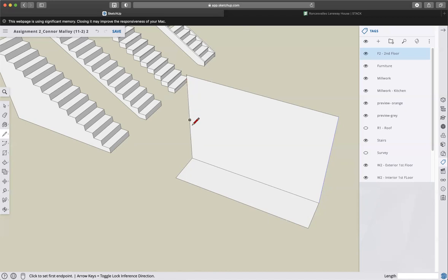The left-hand side is still one line segment. If I go to this side, every green is the endpoint. Those are now, that one side of that wall is now 15 separate segments. And that represents the height of each riser. So if I have 15 risers, that means I have 14 treads, because the last tread is really the top of the second floor.